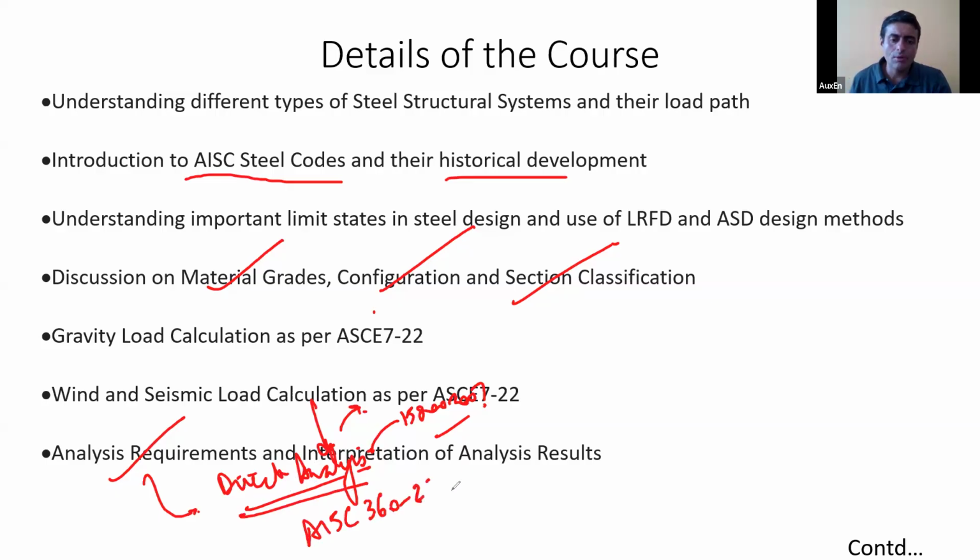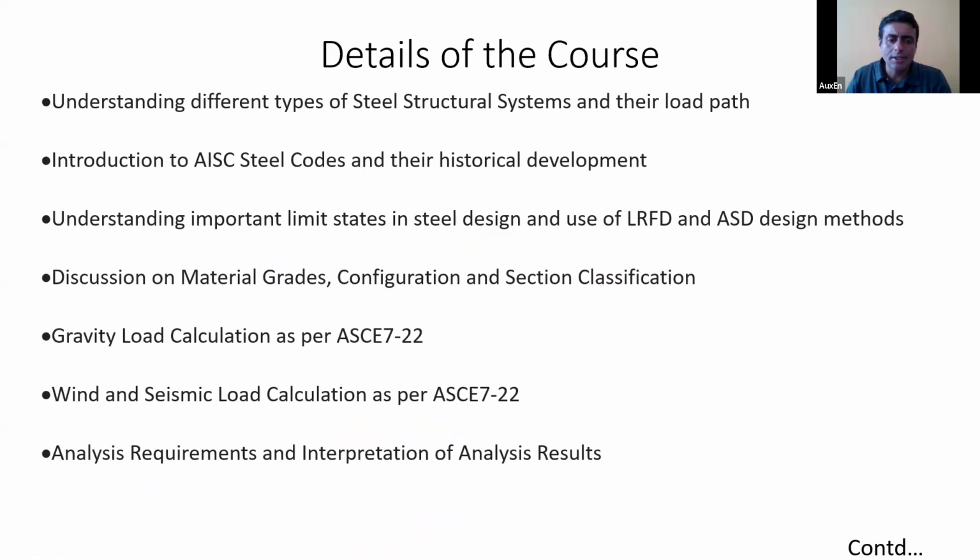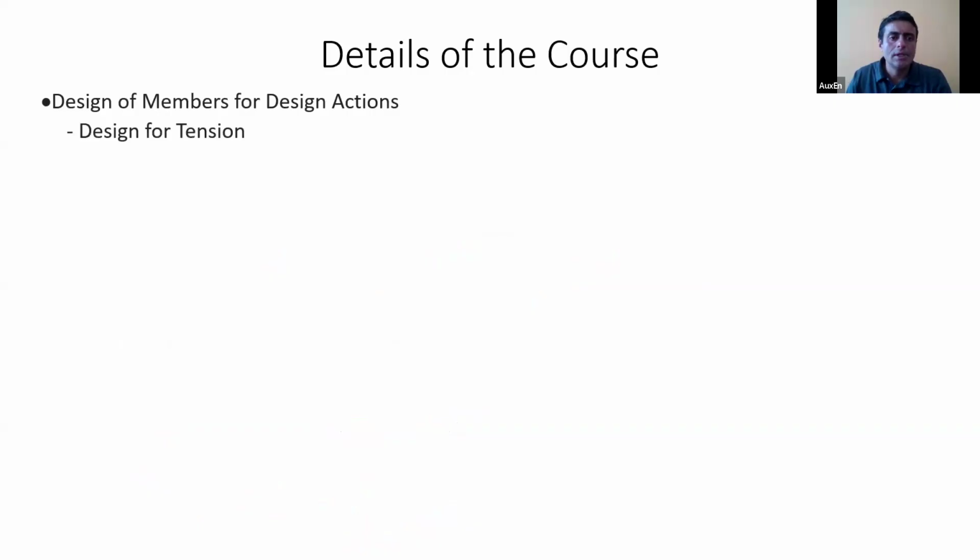And we get to know a lot of things about the direct analysis method and how to perform it in the software. So this we will focus on when I say the analysis requirements. We'll focus a lot on it. It is covered under chapter C of AISC 360, the analysis methods.